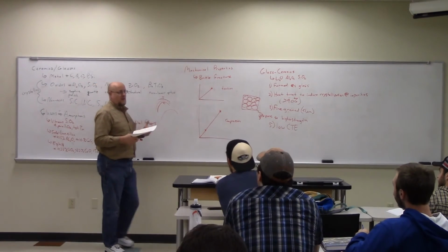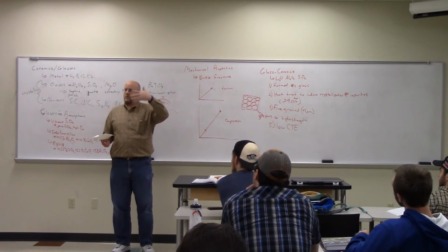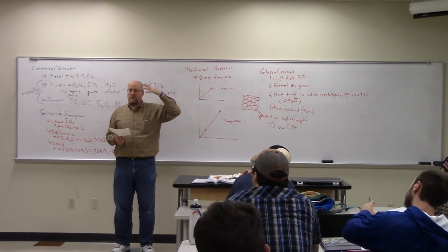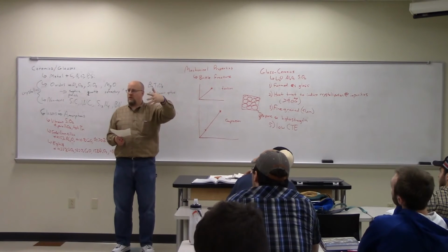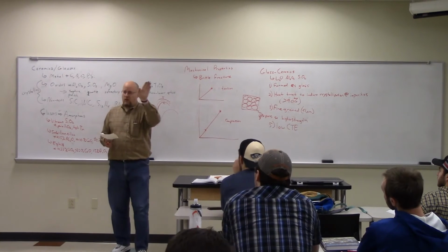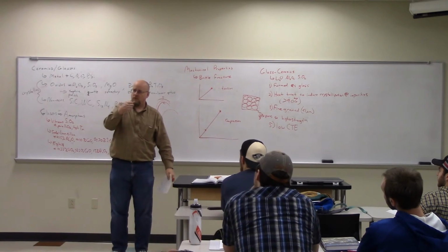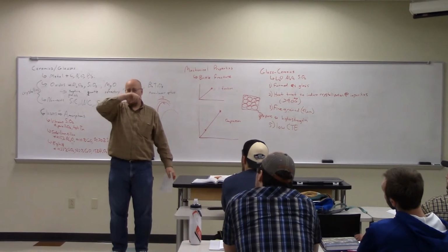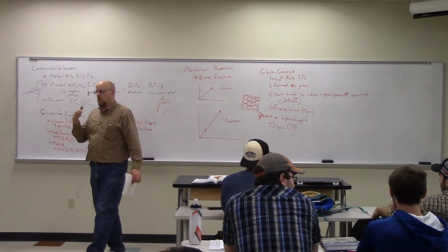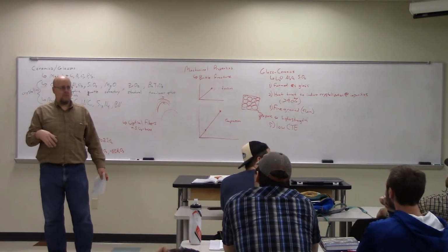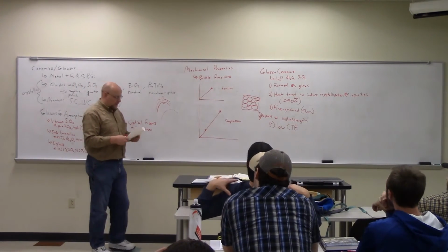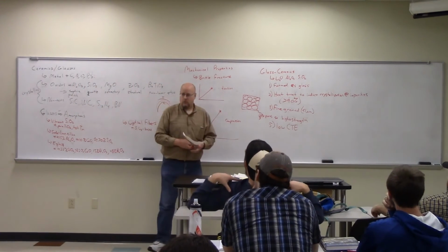I'm guessing it's probably because I have light going from one crystal to the next crystal to the next, and crystals, as we'll talk about in just a second, don't have a uniform refractive index in all directions. They're anisotropic, so the light scatters around, it bends. Every time it goes through a new crystal, it bends to a different angle. And so the process of doing that causes the light over many small grains to randomize and scatter in multiple directions. That's why I'm guessing it's white. I doubt that it's related to the titanium.